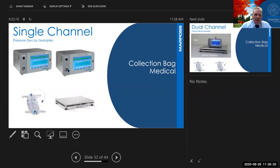Collection bags, this is the one I was talking about where we actually constrain the package. Because this blows up like a balloon, we actually put this between two plates to do a leak test. This particular fixture is a 2-channel fixture, meaning we can test 2 parts. And if we're going to do that with single channel testers, we would have 2 testers to do that, and that allows you to run them asynchronously. Load one, test it, unload the other, and then test that one, and just keep them running that way. So a lot of times this will be a typical medical single channel configuration.